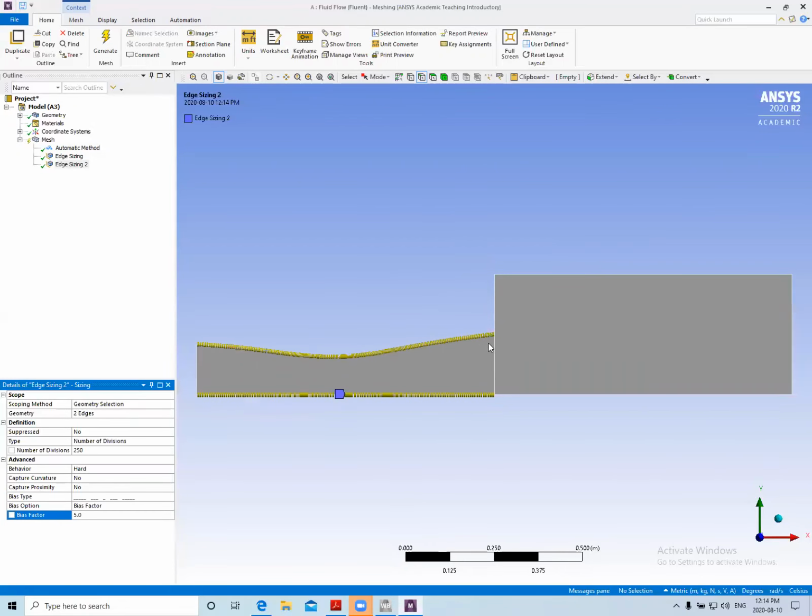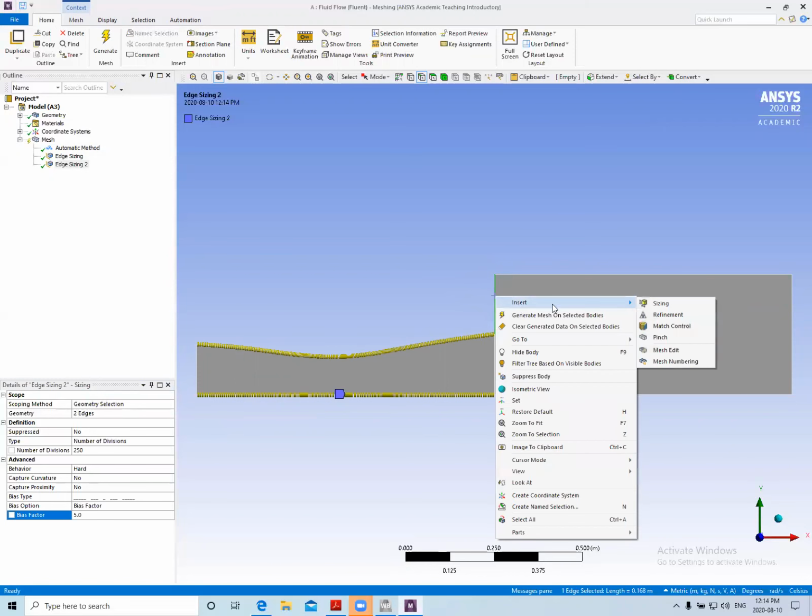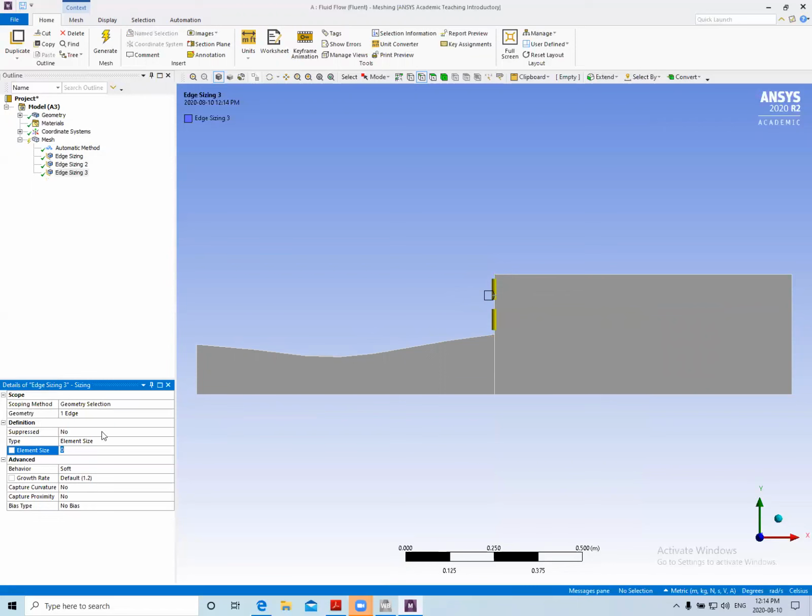And here I gave 50 points. I'm gonna give the 50 points for this wall as well, this line. All right. The number of points is 50. Now, the number of points in the right boundary should be the same as the summation of this line and this line. So I gave 50 for each of them.